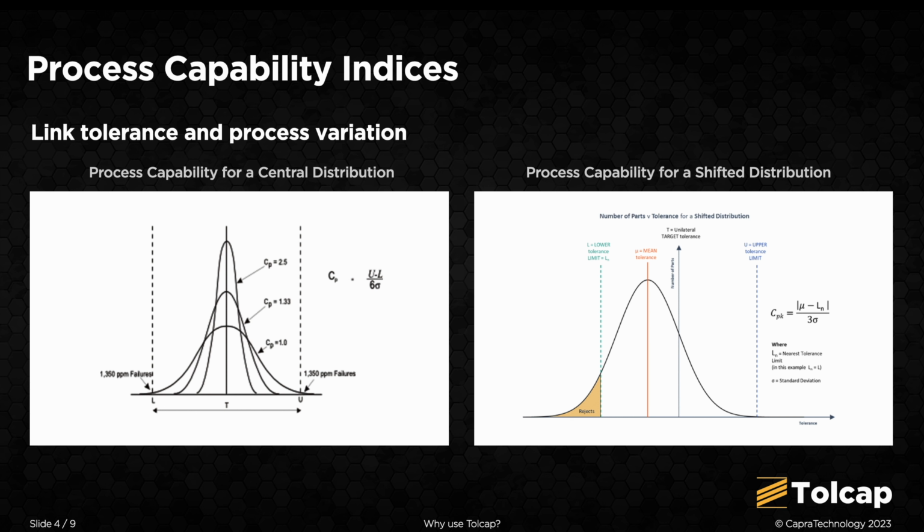Measuring manufacturing process capability involves maths, and I'm hoping you know the basic statistics of mean and standard deviation. If not, if we were to measure a particular dimension on a number of parts, the mean would be the average of the measurements. The standard deviation is a measure of the variability of the measurements. Take each one, subtract the mean, square the result, add up all the squared errors and divide by the number of measurements, and then take the square root. The universal symbol for standard deviation is the Greek letter sigma, and we always call it that.